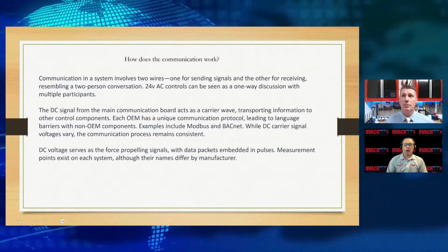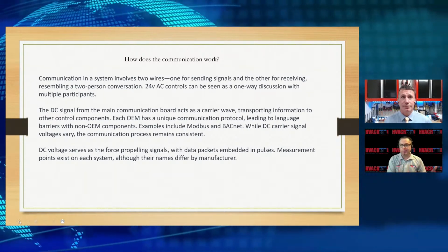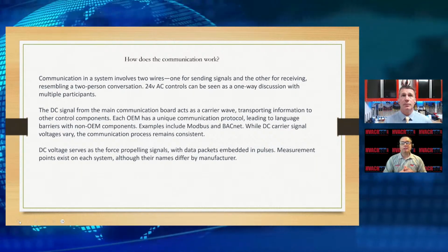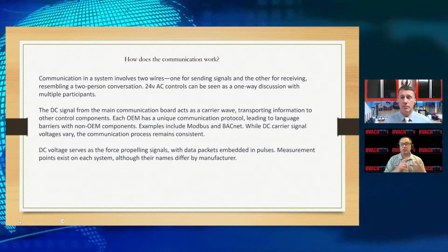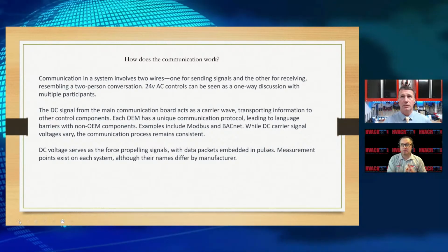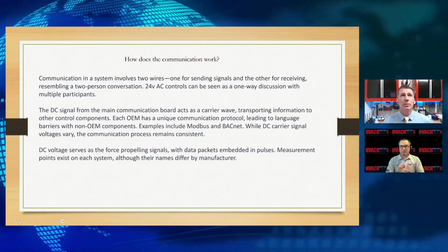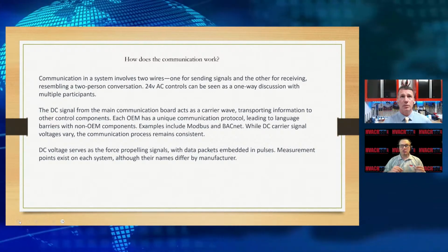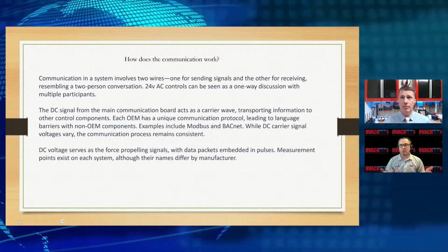That protocol will speak to that controller or module, or the PC board that is communicating with inputs, outputs. We're going to get signals from thermistors, pressure transducers, and calculate all of them, do things with them. It's going to say, hey, at this pressure, at this temperature, do this, or do this when you get to these pressures or temperatures, or whatever it might be.